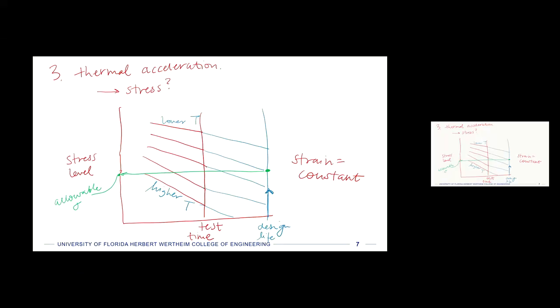And so many of these experiments were done, and as researchers do, they tried to come up with ways of quantifying the trends that they saw, right? So the first model that the book tells us about is called the Larson-Miller parameter. All right, so Larson-Miller parameter. And the reason that it's not called a model is that we don't have a particular model for this, but we know a few things are important. We know temperature is important. We know time is important.